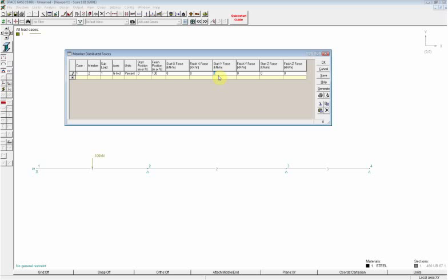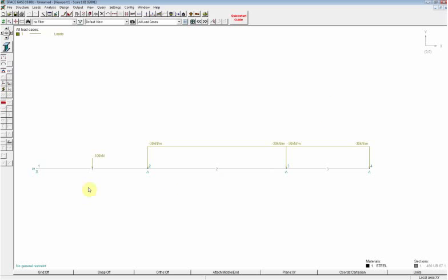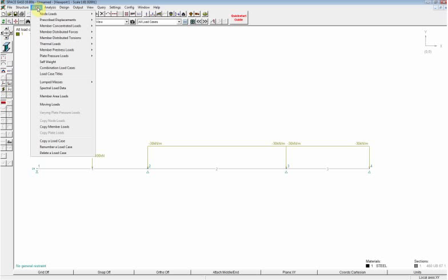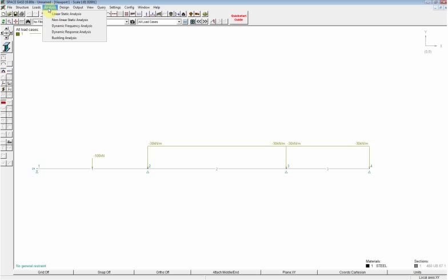So its start will be negative 30 kilonewtons per meter, and so will its finishing force. Okay, so case 1, member 3, exactly the same thing. Negative 30. Cool. Hit OK. So now SpaceGass has depicted all of our loads acting on the structure. There's not really anything else we need to put in here yet.